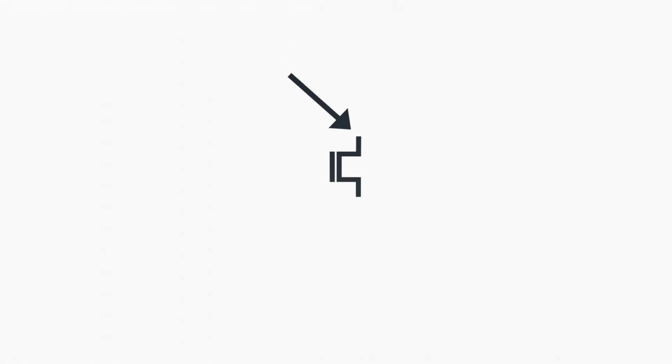It's also important to understand where they actually come from. These are transistors. We have the PMOS transistor and the NMOS transistor. The physics behind how they work is complicated, so for now, let's focus on how to use them, which is pretty simple. For an NMOS transistor, you have a gate voltage here, which is a sort of input. This top side is called the drain and this bottom side is called the source.